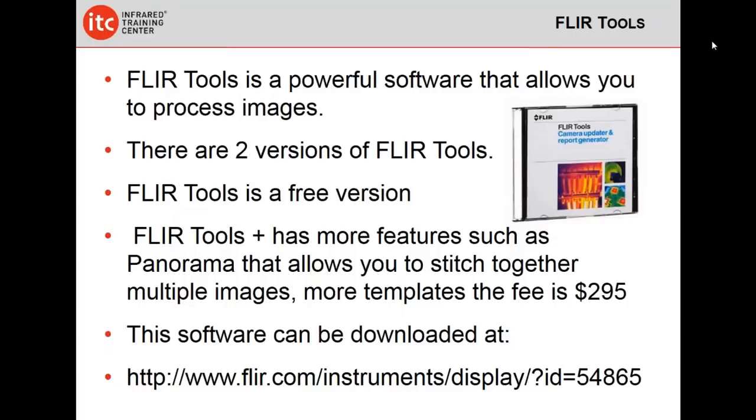FLIR Tools Plus has added features, meaning more color palettes, more measurement tools. The biggest feature that I think FLIR Tools Plus offers, which is an amazing feature, is called Panorama. And we'll look at an image of Panorama here in just a few minutes. But Panorama allows us to take multiple still images and stitch them together in one image radiometrically. So this is a huge advantage when we're working from the air. And I've had a lot of questions about, can I process my video in FLIR Tools? And the answer is no, you cannot. It only processes still images.